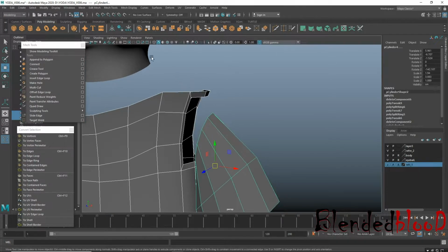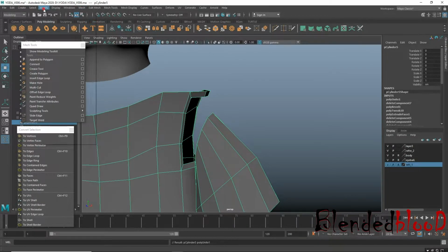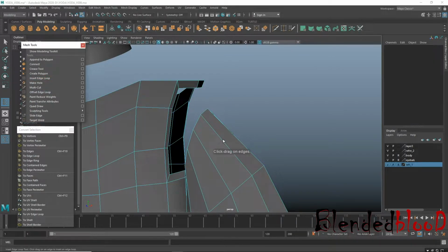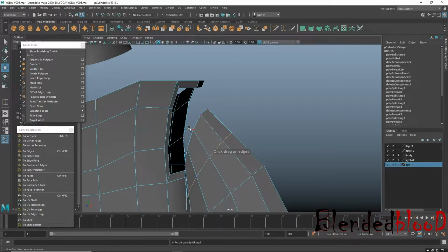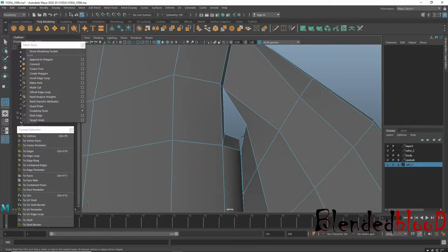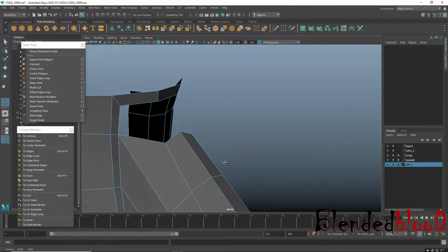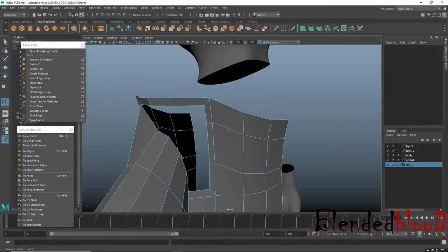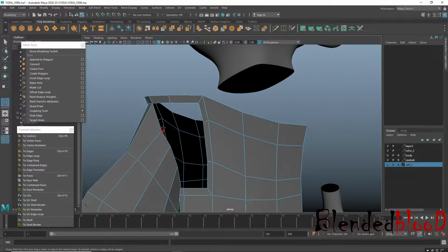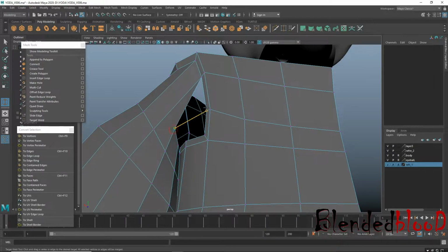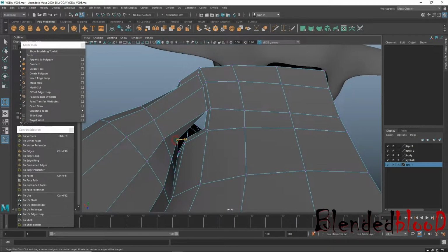First select these two, mesh, combine, modify, center pivot. Right, come to edge, insert edge over here, just put a loop. Now come to vertex, go for target weld, drag these to this, because at the end of this extrusion we have to go for the surface sculpt geometry tool, so that will maintain our mesh loop, mesh flow or edge loop. I always confuse these two words.